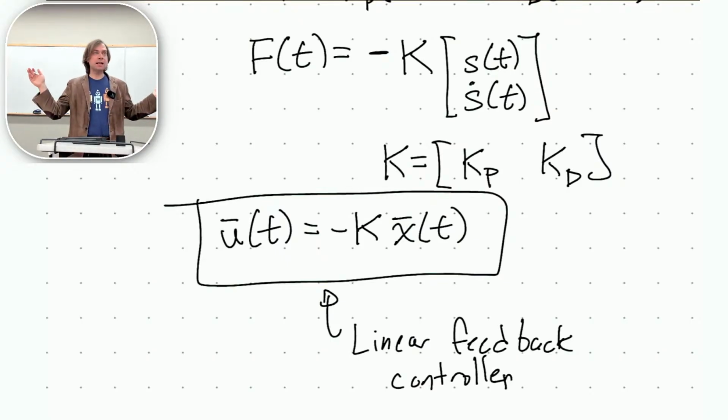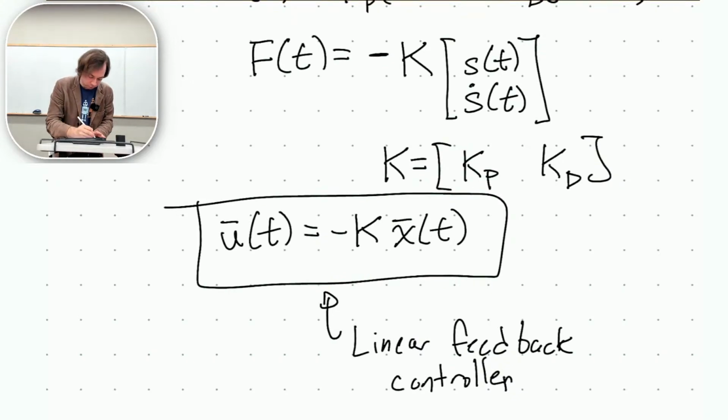Who here has done a PD controller before? You wrote a fantastic one. They're super easy. You multiply the thing you want to control, that error, by a constant. Then you add the derivative of that times another constant. Proportional derivative, PD control. I think I should write out proportional derivative.